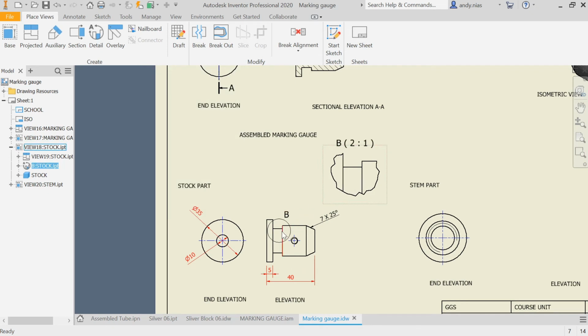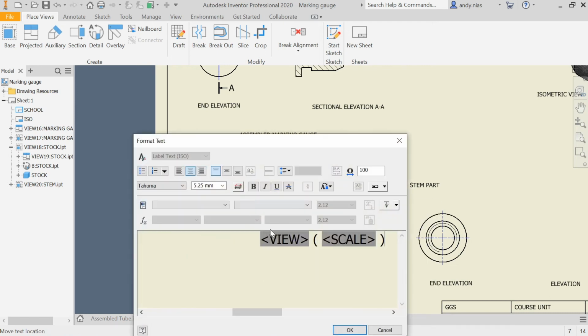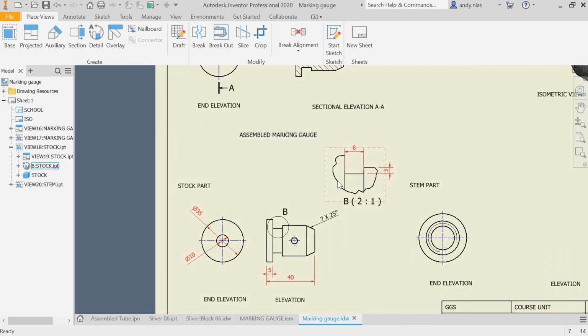So you can see now that bit there has been enlarged. You can move this if you need to. You can drag these in or out if you want to get a tighter or bigger, wider view. And now on there I can add some dimensions if I want to show what the dimension of this step is. The label, you can move that, you can edit the label, you can give it a name or what have you.